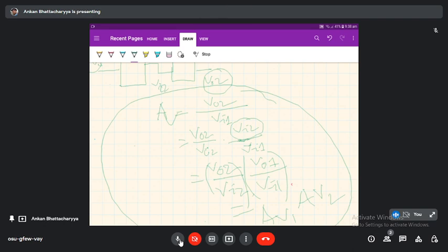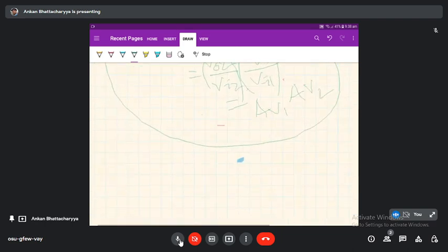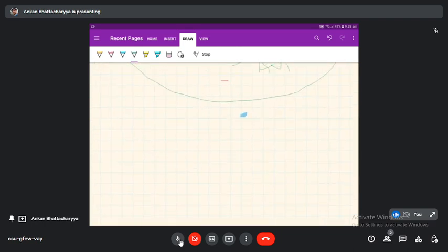Now in voltage amplification, the CE mode of the transistor is used mainly. Why? Because the voltage gain of the CC configuration, that is the common collector configuration, is not suitable for cascading since the voltage gain is less than unity.